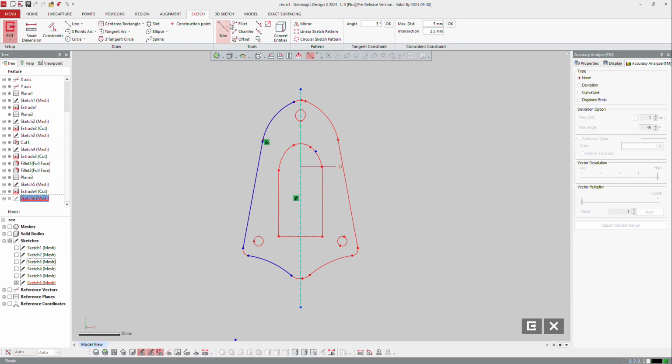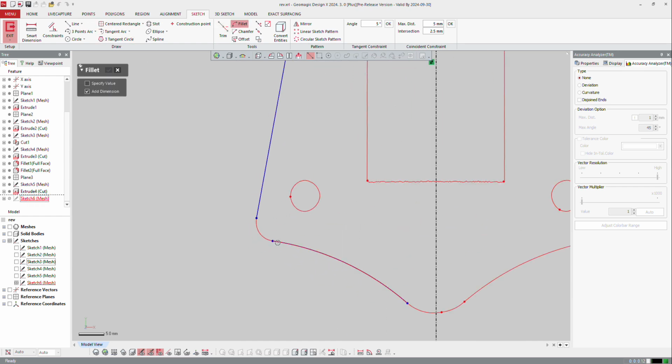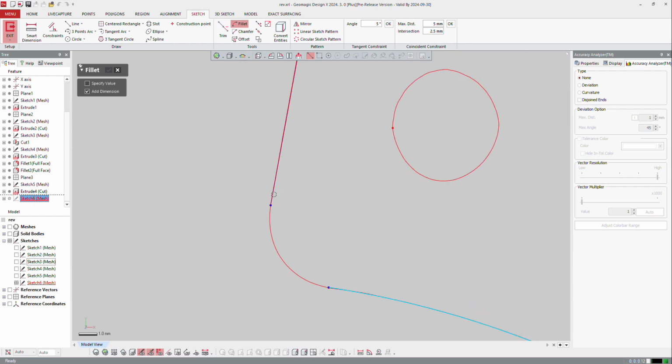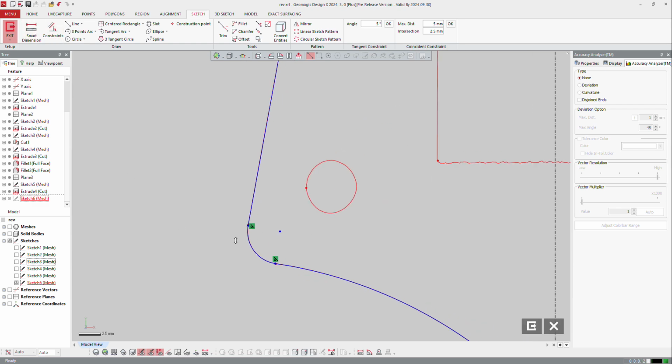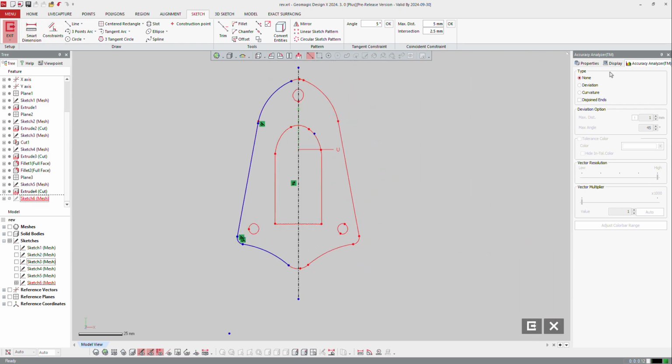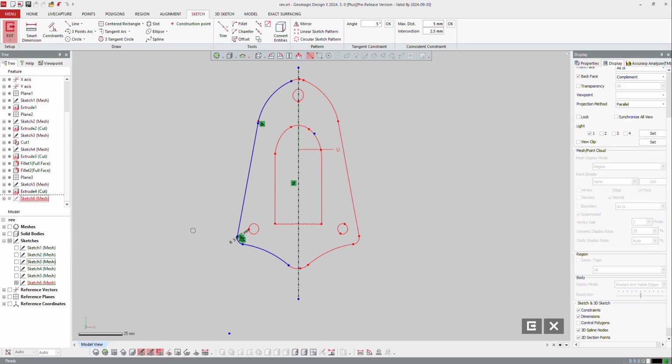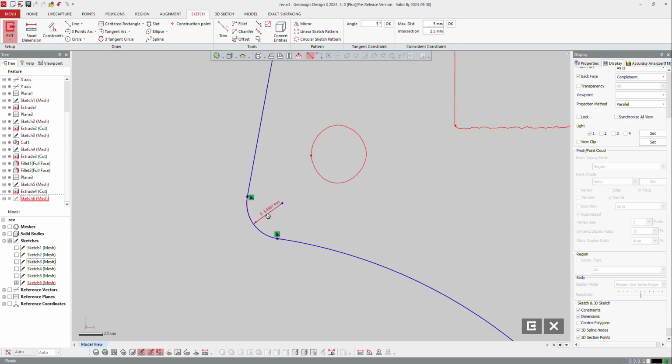And then here I will just create a fillet from here by zooming to there, and I just make sure that it's accurate enough. Of course, here it gives me, oh, I forgot about the radius, but it gives me radius. Anyway, I can display or not the dimension. So here the dimension is there, and I can round the values to 3.7 millimeters.